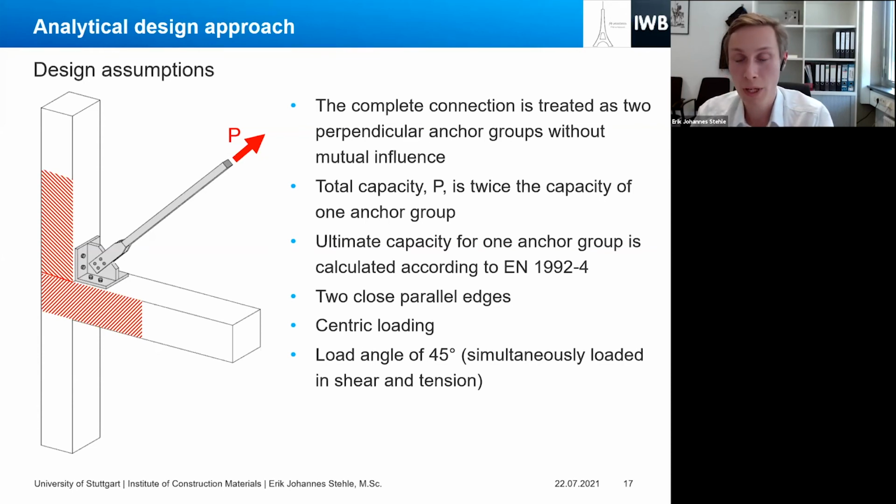So what happens when the steel bracing is in tension, we have an inward bending of the beams and the columns. So the cracks will actually close. So there will be no cracks or no crack opening when the anchors are loaded.